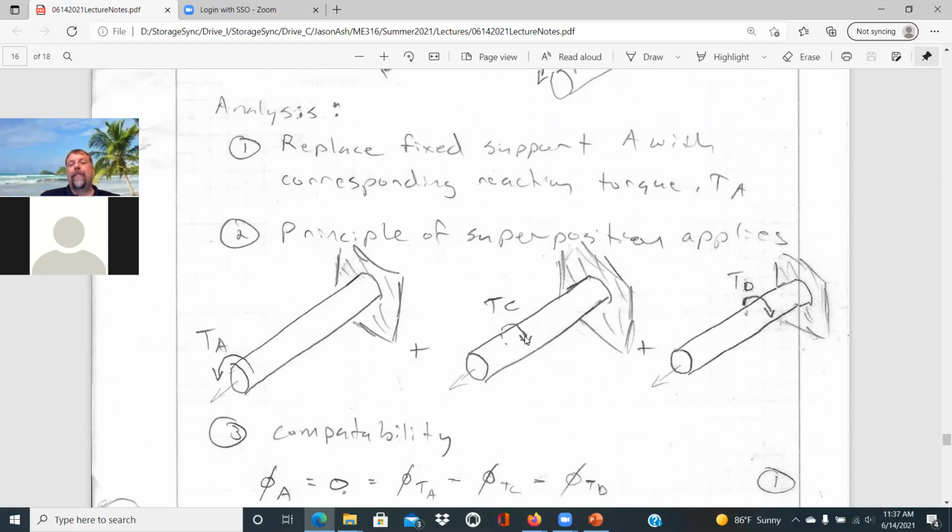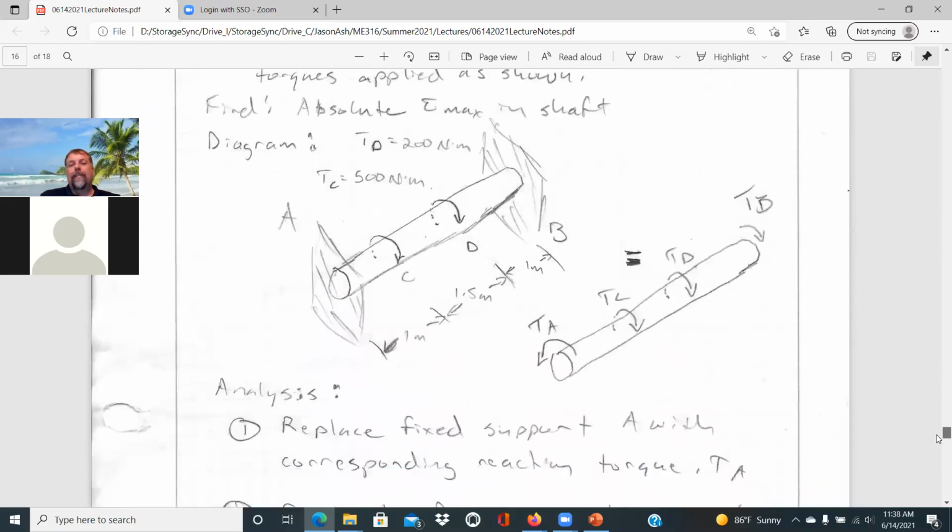That would act over approximately 2/3 of the shaft, everything towards the fixed end. This is free at this point to the left, so it's not going to cause any changes to that section. And TD would cause a twist for that final third of shaft nearest the base. And I'm sure the values for those lengths are not quite thirds, but